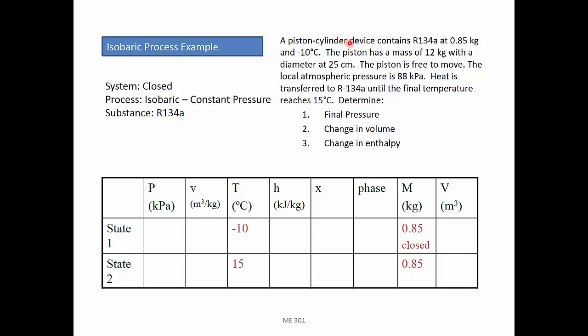Since this is a piston cylinder device, the weight of the piston, the area of the piston, and the external pressure will all remain the same in this particular case. The process is isobaric, which means that the pressure will remain constant throughout the problem.